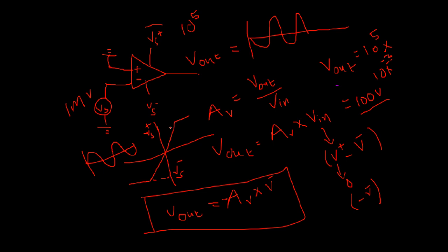So it will be saturated depending on the external source voltage we have given to the Opamp. This is the linear region, so the output varies linearly with respect to input. We need to make this Opamp operate in the linear region in order to use this Opamp as an amplifier.